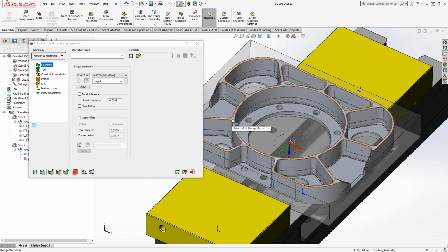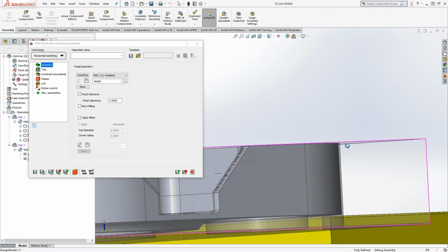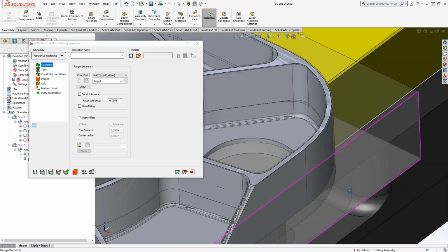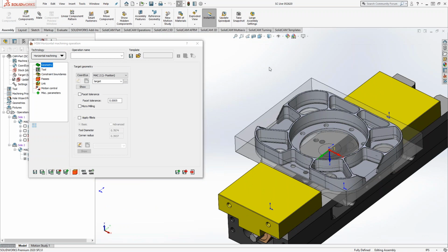Well, and even look at what Mark is talking about doing the top. We don't have any stock up there. That's kind of how we did it, or how Mark set up the stock. Oh yeah, that's true. So I guess there is no reason to even finish that up there. But since Mark only left that 20 thou on the wall as well as the floor, with this horizontal we can do it all in one cut.